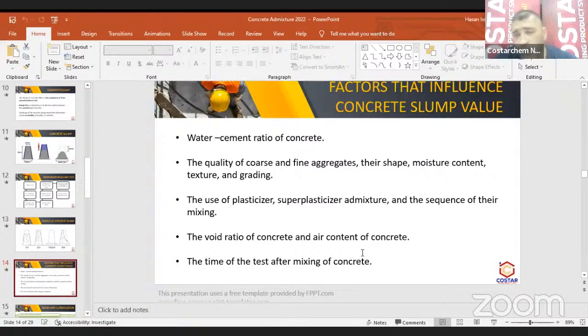So what it does basically is entrap and disrupt the capillary system of the concrete. When water is going in and trying to penetrate the surface of the concrete, it will go inside this void or bubble, and there's no place else for it to go. So that's one.